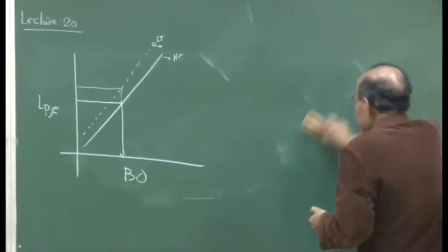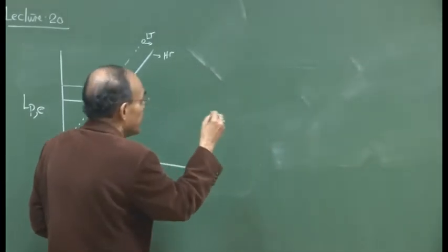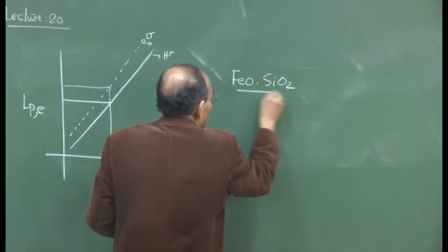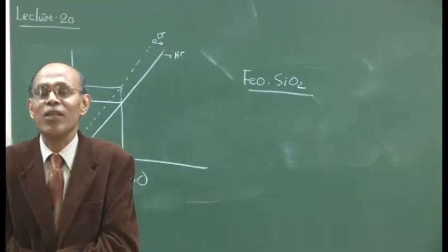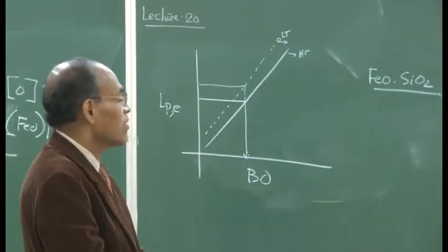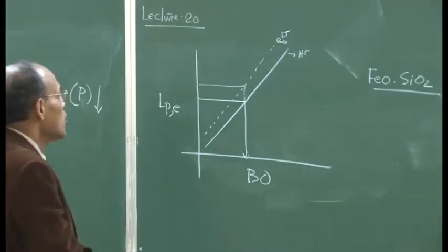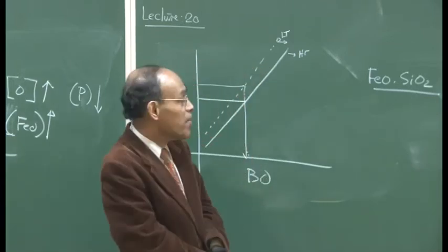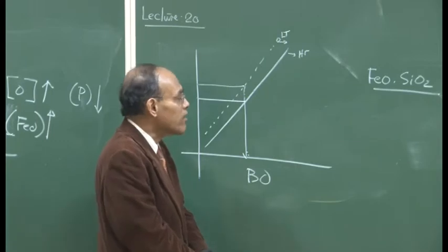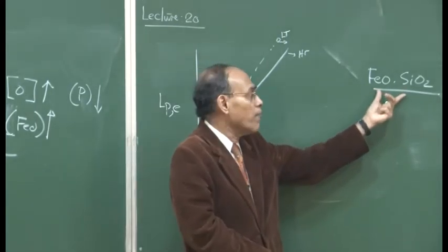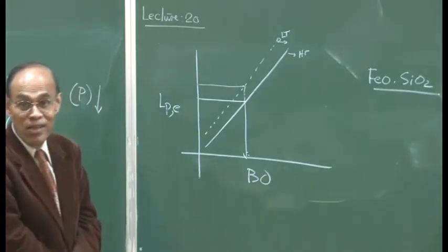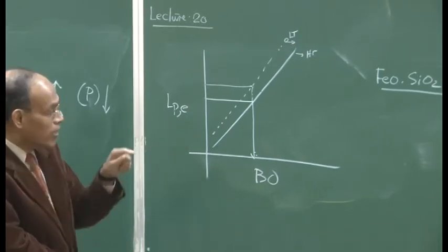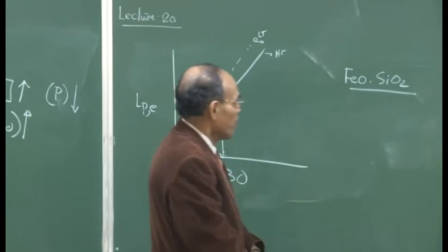So, basicity initially we must understand; we will talk about this in greater detail later on. We have the slag that forms as I have indicated. The moment you start putting in oxygen, because of the large affinity of silicon towards oxygen, you will get spontaneous and rapid oxidation of silicon to silica. Similarly, iron being the bulk, 95% of the melt, forms iron oxide, and this is very easily formed. We have seen in the blast furnace, in the cohesive zone, the first slag to appear at relatively low temperature; this is the slag phase that is going to be generated.